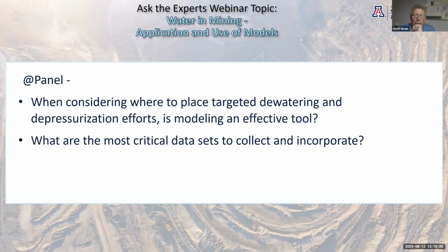And if you're in a porous media and it's a dewatering well, you try and target the areas of greatest saturated thickness. If you're in fractured rock, you've got to go and pre-drill the fractures. And remember, it's not just a question of hitting fractures. The deeper you hit them, the more sustained the yield of the well. So the answer to the question, I think, is generally yes, specifically no.